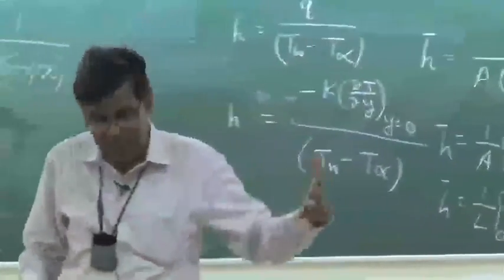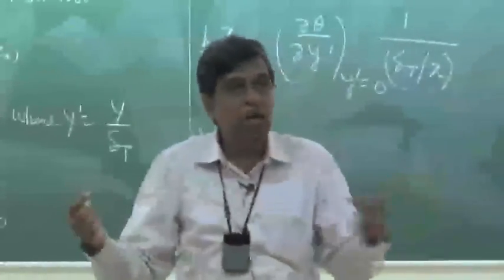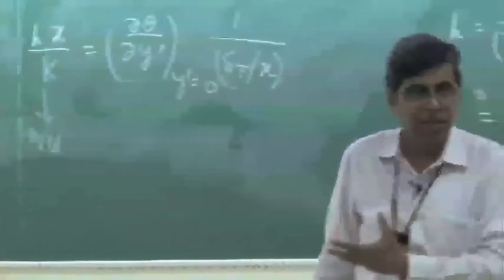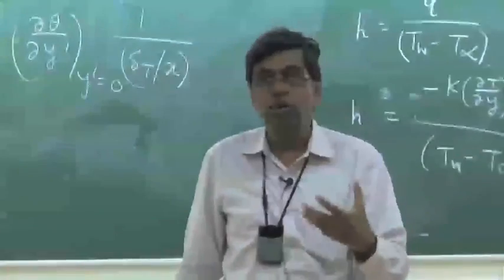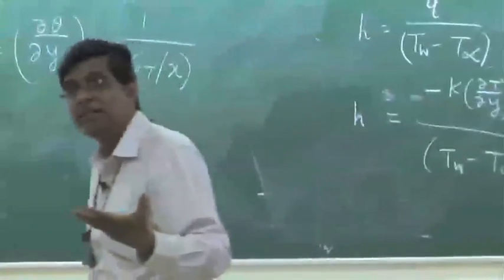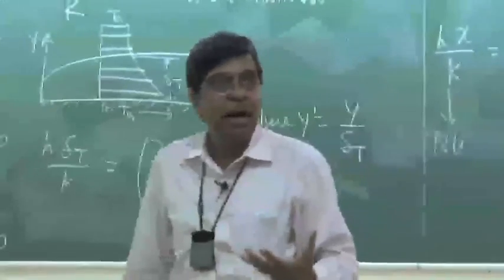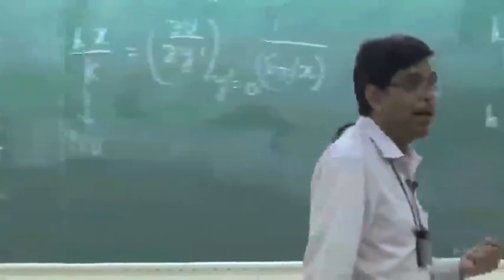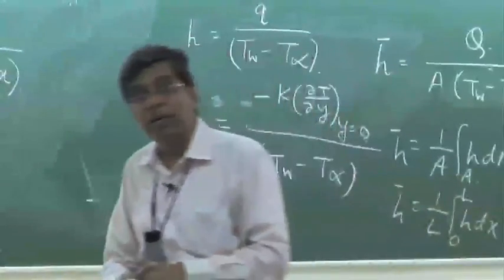But when there is a flow of fluid and we take an element, along with the conduction, we have to consider the advection of energy, which is very important. As I told, the advection of energy, total energy, comprises internal energy, that is intermolecular energy, plus kinetic energy and the potential energy, plus the flow work. All these things have to be taken together.